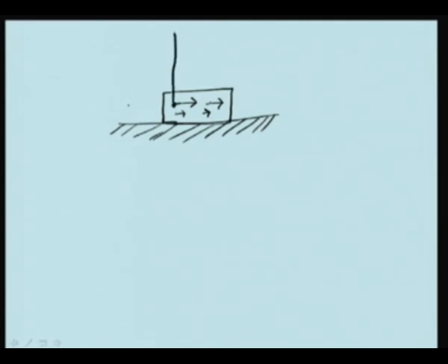Here one perpendicular line, another perpendicular line. The two lines are parallel and they never intersect. However, we can consider that they intersect at infinity. Thus, the instantaneous center of rotation of a translating body is at infinity.